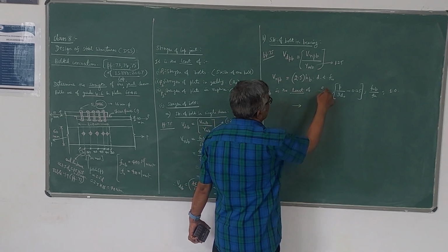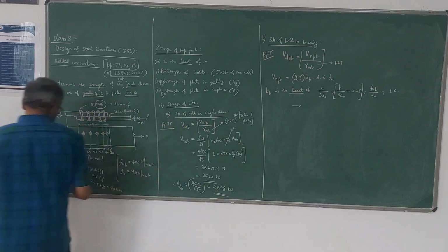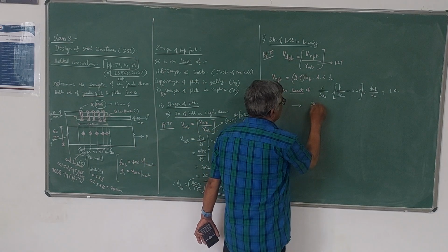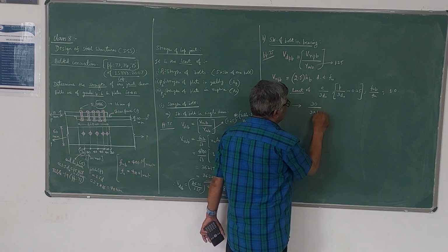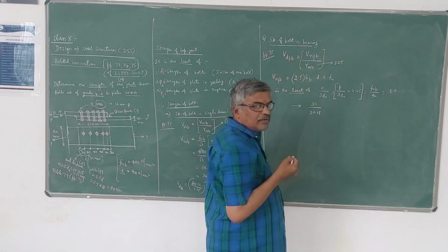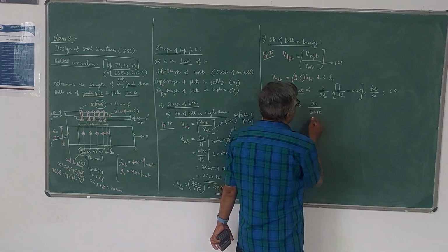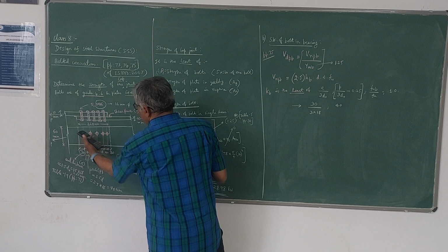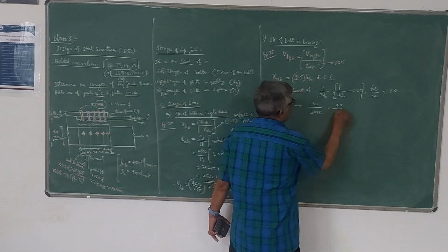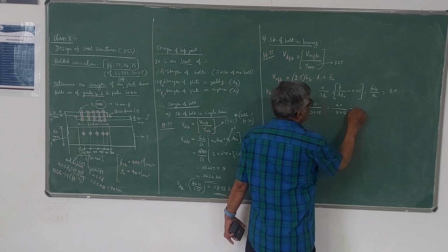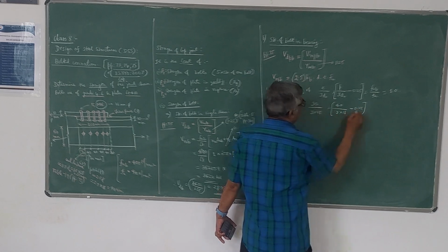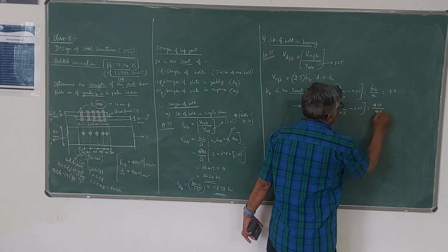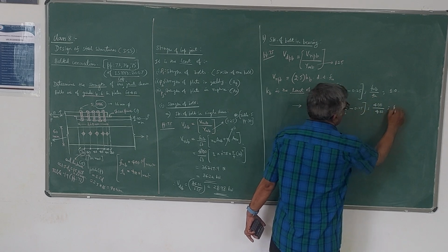Now let us calculate this. E here is the end distance, 30 mm. In this problem it is given as 30 mm. 30 divided by 3 into 18. d0 is 18, d is 16. d0 is the diameter of the bolt hole. We have to add 2 mm clearance for that, so 18. Then p, pitch, is here 40 mm. Distance from center to center of the bolt is 40. Divided by, once again, 3 into 18 minus 0.25. Then the third value is fub, the design tensile strength of the bolt, divided by fu, the tensile strength of the plate, that is 410, and last value is 1.